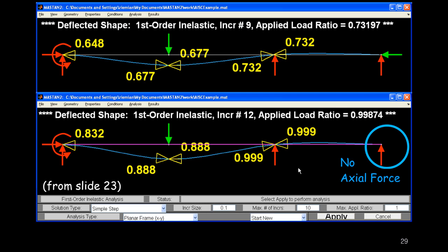Those P-delta effects are going to come to life when we start to account for them, or run what's called a second order inelastic analysis. But before doing that, I need to take off and introduce just the topic of second order elastic analysis, and then I'll come back and look at this second order inelastic as the attendee is asking about. Okay, and then let's do one more question. Go to slide 30, please.